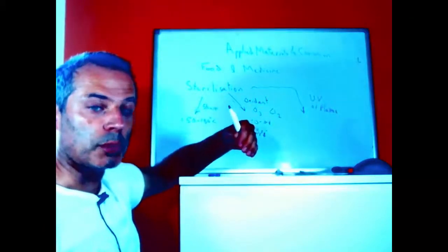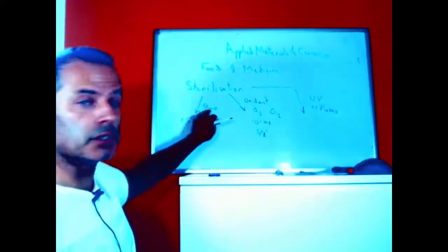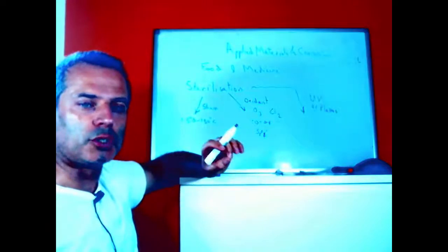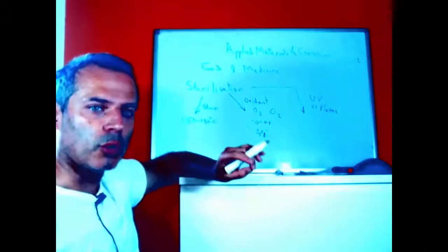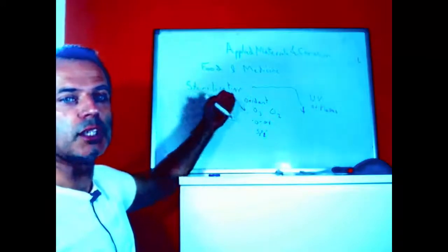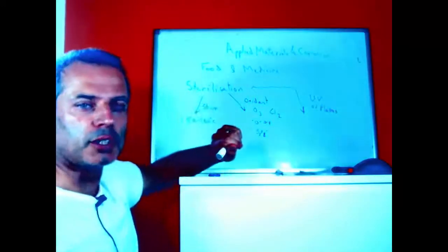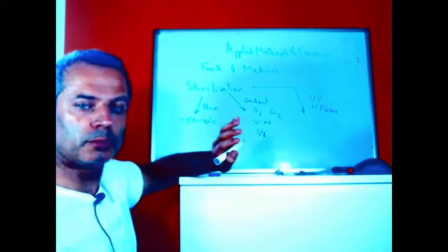When we heat water up enough, it becomes quite oxidizing. As we heat water up, the properties change and it becomes more and more oxidizing, and that makes our metals, for example, less and less able to sustain it. So steam is quite brutal.